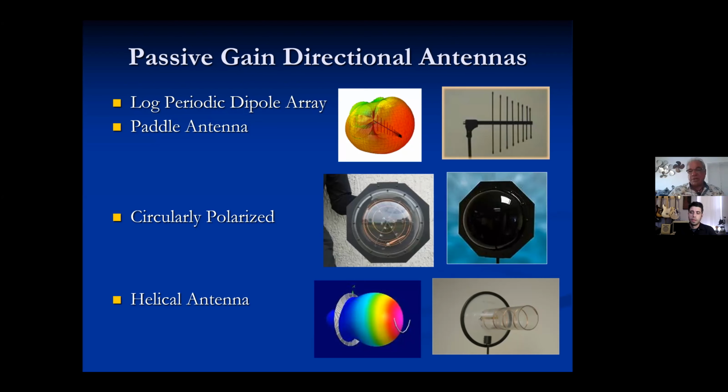And I tested this out multiple times with a spectrum analyzer in my hand, walking from antenna to antenna. And by the way, that switch occurs so fast that A, the electronics in the in-ear receiver can't pick it up, and B, even if it could, our human ears couldn't pick it up psychoacoustically. So that's another trick if you have a really wide stage. More to the point of the question, helical versus CP.